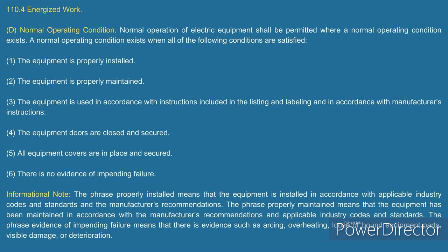But I also will say I'm in a hazardous location and I'm classifying a location. The installation that's going in there depends on the classification of the location. You're not going to do all that in the National Electrical Code Articles 500, 501, 502, 503, and 504. Most of the time you're going to determine the location from NFPA 497 and 499. You see what I'm saying? So that's what we're talking about when the phrase states properly installed.